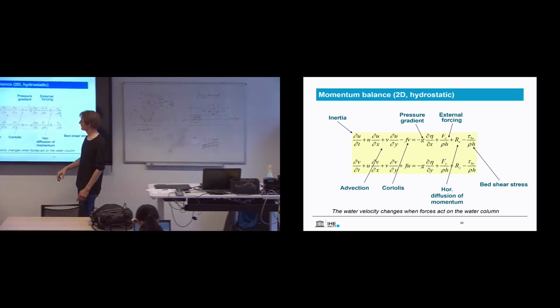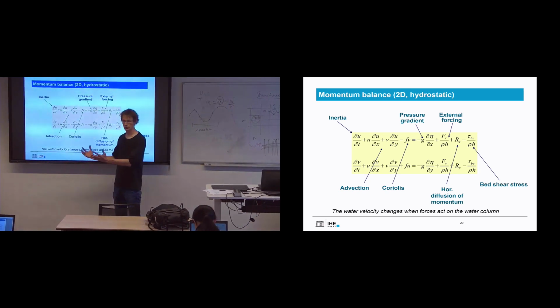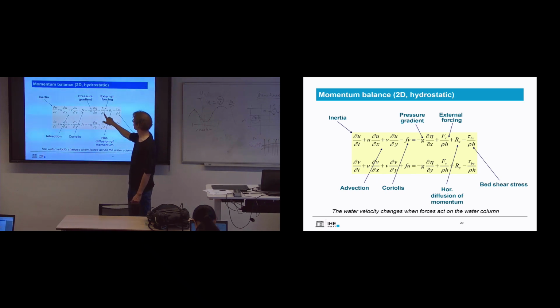equations, then at the end of the simulation we are in a stationary condition, which means that this all drops out. Coriolis doesn't matter here in this case. We have an external forcing, we have a water level gradient, you saw that, the red block means water is higher in one corner than the rest of the model. We don't have diffusion, and we don't take into account bottom shear stress for now, so basically what we get in the end is purely a balance between the water level gradient and the wind that's forcing the water level. And that's what you get then.